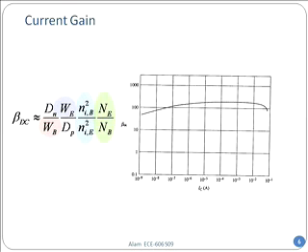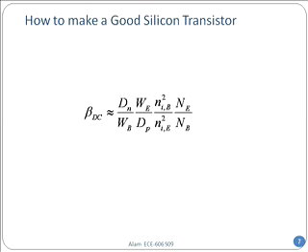In the lower side, because of the base recombination, you should go back and take a look in the previous slide. Because of the base recombination, the base current is very high compared to the collector current. As a result, there is a roll off also in the lower side. So this is our main object of analysis, and from the next 4 classes, I am just going to bring this formula up over and over again, and everything that you have to understand about bipolar, how it operates, all is in here. There are in fact at least 2 Nobel Prizes, maybe even 3 in this formula.